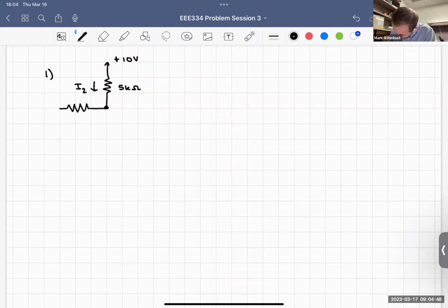So we're going to have a 10 kilo ohm resistor there. Going to go down, I'm going to add a little more. So right here is going to be our gate voltage, which will go here and then into our MOSFET. Go down, and then I'll toss our arrow there. Now, I won't say it yet, but you can think to yourself whether this is an NMOS or a PMOS.